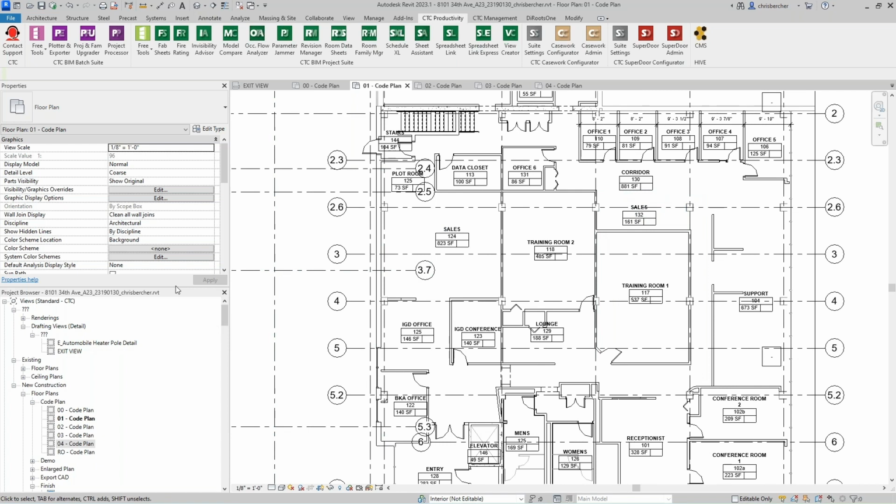A couple of things you need to do to set this up so that the tool knows what to use. You need to have the rating specified in the wall for it to know what pattern to associate with it. You also need to make sure you have the tag loaded in that you want to use.